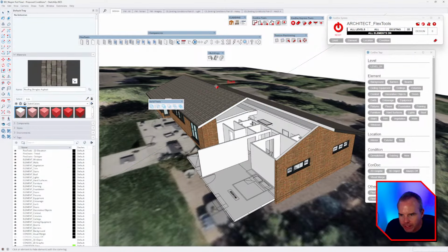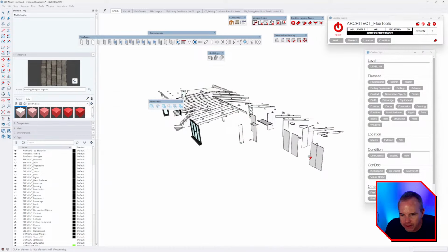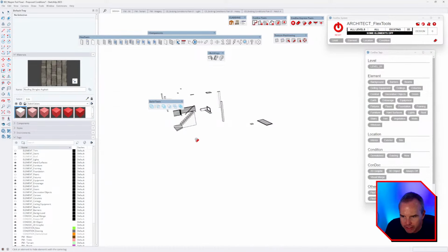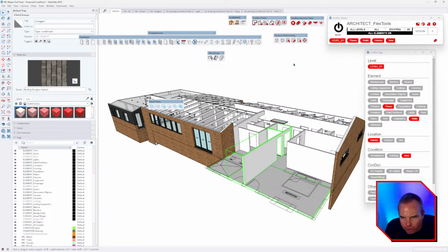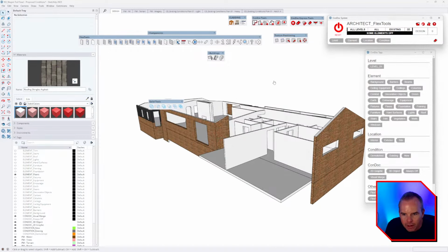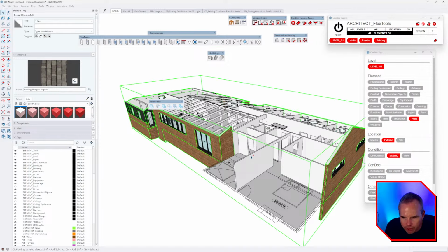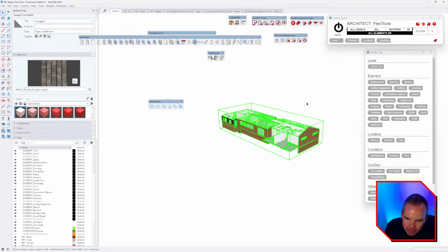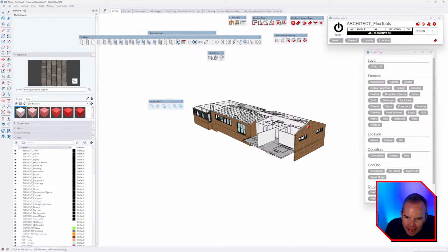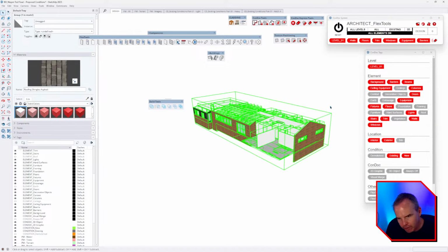So like element tag freeze, I can just turn things off, so this is turning off the tags by just clicking on objects. And if I hit reset, I can isolate my floors and my walls by hitting tag isolate, like that. If I were to take all this stuff and group it, like this, and now my tag freeze doesn't reach through. So anyways, that's one reason I wouldn't like to use it.